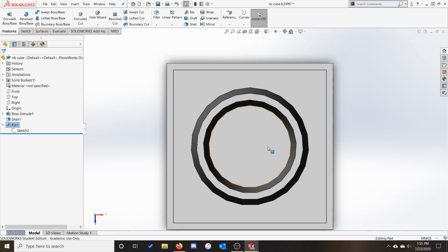However, if you are not using the natural end condition, you do need to fully define the endpoints of your arcs, as the implied tangent edge will be underdefined if the arc endpoints are left floating. RIB works by extending the endpoints of your given sketch until they hit something, and it does this until it's fully blocked by your object.